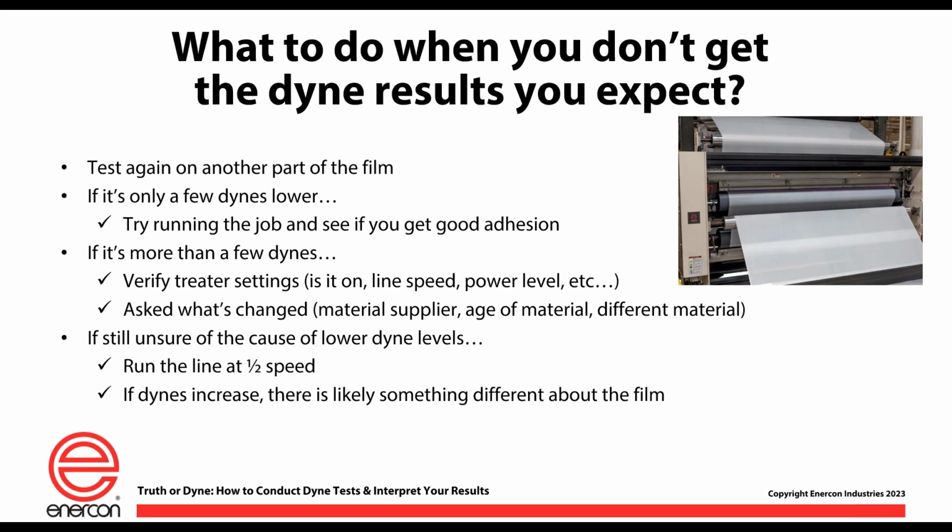If you're only reading a couple of Dynes difference one way or another, you probably shouldn't be worried about it, because chances are they're still getting good adhesion. You're not seeing an issue like in the dog photo where the printed area or the liquid you're applying is all spotted and not wet. So don't get hung up on a couple of Dynes and start chasing that rabbit hole, because that'll take a lot of time out of your day and you're not going to net anything at the end of the day when you're done with it.